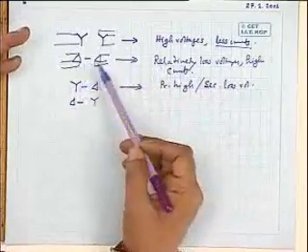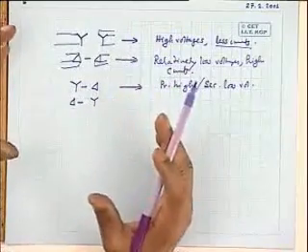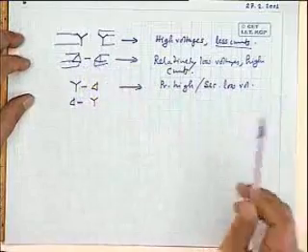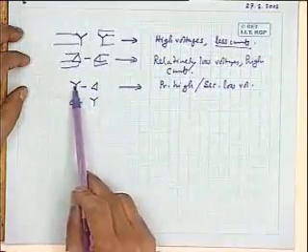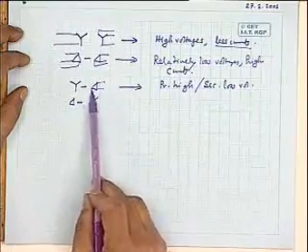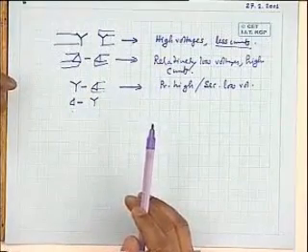What other advantages? One open delta connected thing you can do, of course, provided these three transformers are separate single phase transformers. If it is a three-phase transformer as a whole, one does not do that, because the other winding should be replaced. Then star delta transformer, whether neutral is connected or not, once again is devoid of that problem. Third harmonic problem will not be there, and delta star like that. Zigzag connected transformers are costlier, in the sense that you have to put additional turns on the secondary. This point one can easily understand.